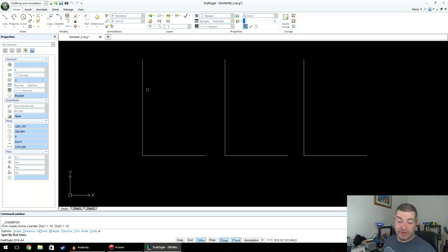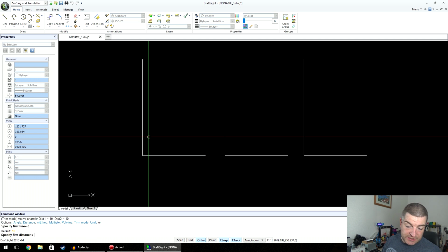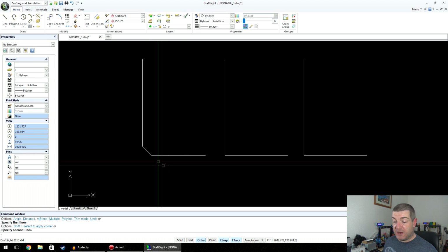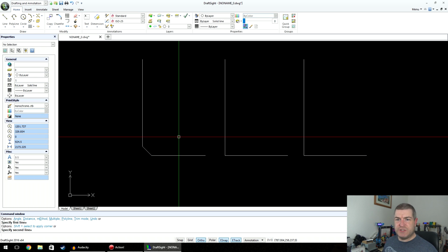So again, chamfer, it says specify first line. Oh, hang on, there's options again. D is distance. So what does that do? D, distance, specify first distance, 50. Specify second distance, 50. Okay, first, second. And we've chopped the corner off at 45 degrees. But what do those distance things do?